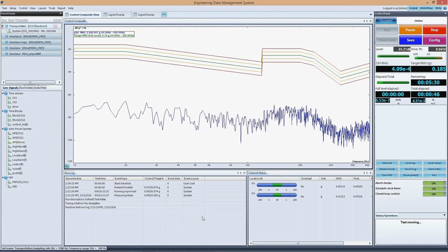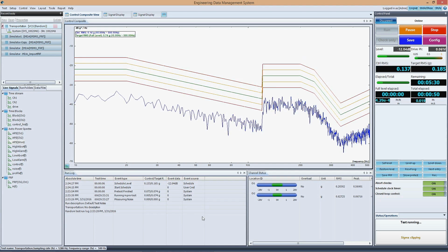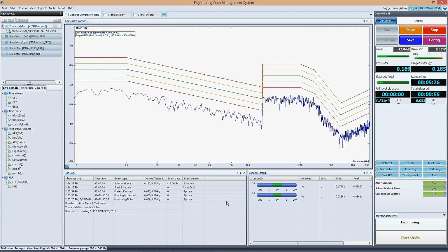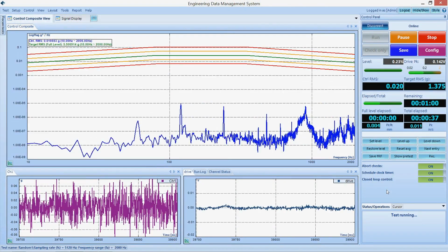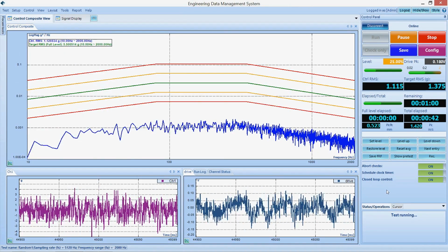If a flat spectrum drive signal excites a shaker and test article, the resulting acceleration response spectrum will not be flat. The armature resonances and the dynamics of the test article will produce peaks and valleys in the resultant spectrum. The goal of the controller is to compensate these peaks and valleys so that the vibration spectrum meets its target. A good controller will closely match the control signal and profile. Slight deviations are expected since the controller is outputting a non-deterministic signal and at the same time controlling that signal.